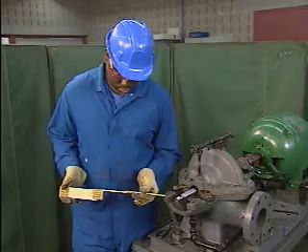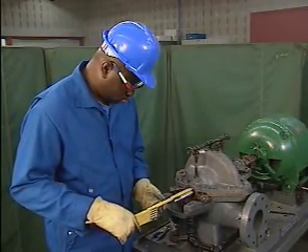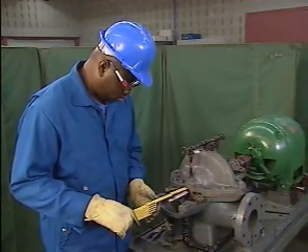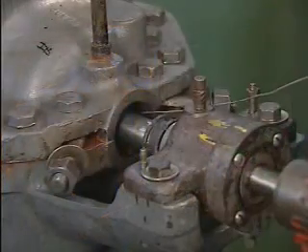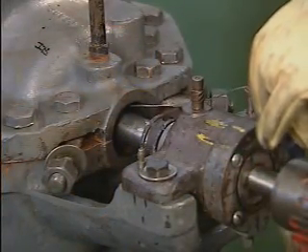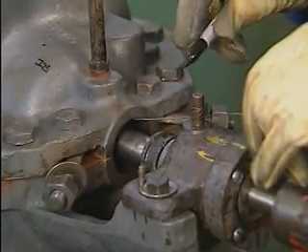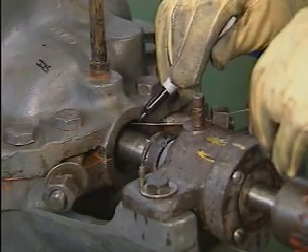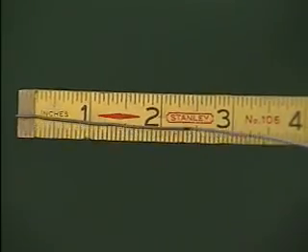Next, the mechanic uses a ruler to measure the depth of the stuffing box to determine how many rings of packing will be needed for this installation. The depth of the stuffing box is the distance, top to bottom, parallel to the shaft. On some applications, it's not possible to directly measure the depth of the stuffing box using a ruler. Instead, the mechanic inserts a stiff piece of wire into the stuffing box and marks the depth on the wire.